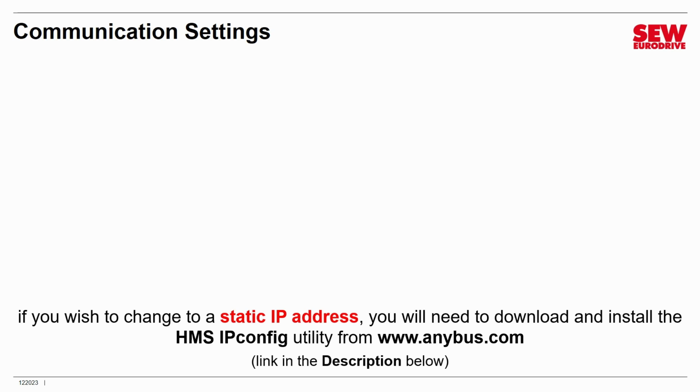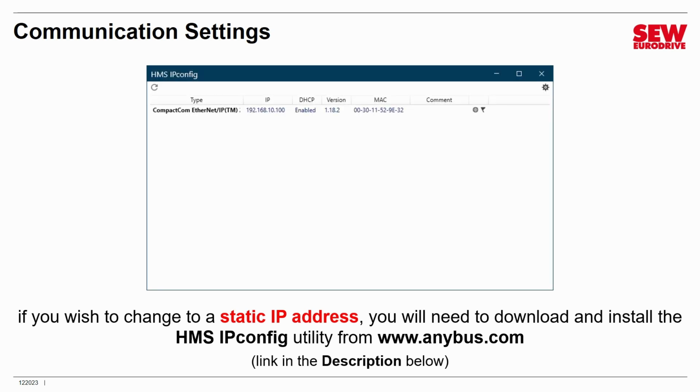Then what you do is you connect your PC's Ethernet card to the Fieldbus card and then fire up the utility. What it will do, it will scan the Ethernet and it will look for any Fieldbus cards that it can detect on the network. In this case, I did it with my Fieldbus card when it was brand new, and it spotted it immediately. It found a Fieldbus card.